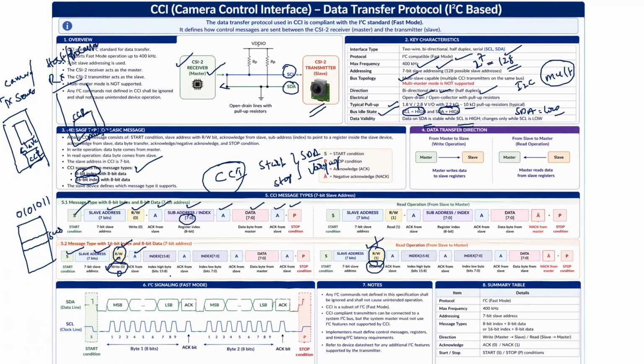Suppose you are doing multiple addresses and multiple data in your slave; then the index address will be automatically incrementing. In that way the next address will be calculated. After we reach that index address, the slave will acknowledge, and then another index value will be taken, which means we are accessing another location in the same slave. That's why we are placing the data.